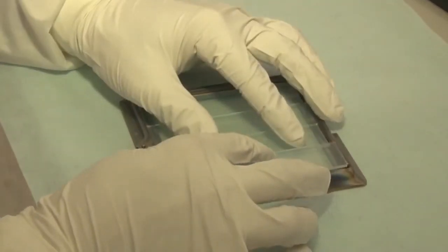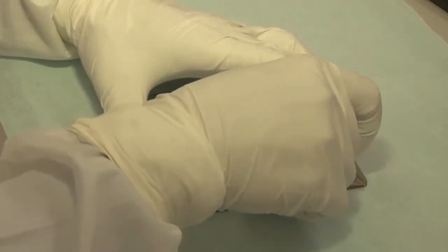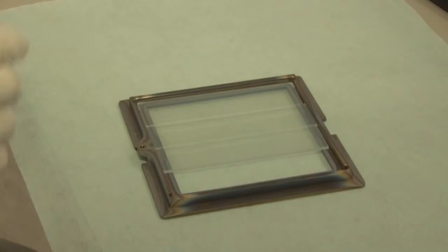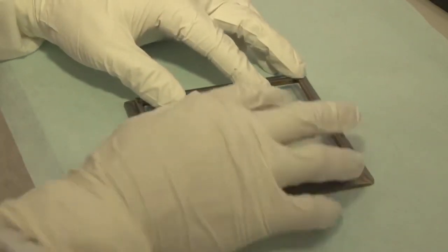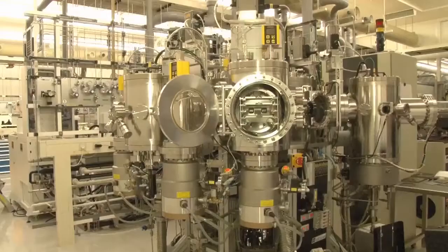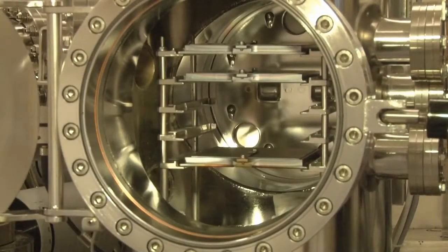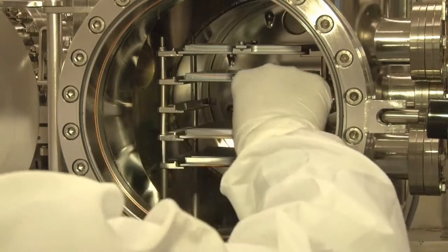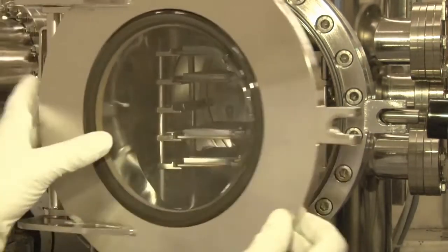This substrate holder is used during the plasma-enhanced chemical vapor deposition step to deposit the various thin silicon films. Again, we use a load lock. The load lock allows access to the various chambers. Every chamber is dedicated to depositing a type of silicon layer: p-type silicon carbide, intrinsic amorphous or nanocrystalline silicon, and n-doped amorphous silicon or n-doped nanocrystalline silicon.